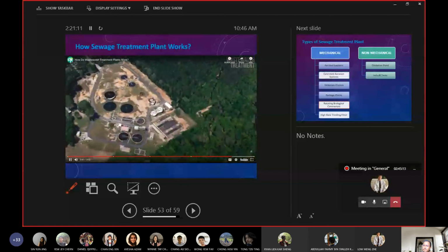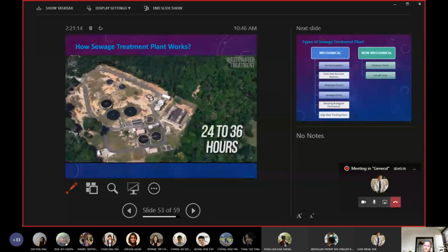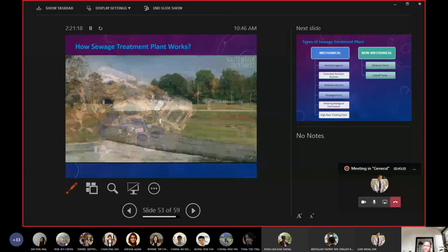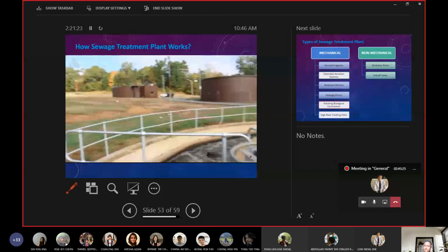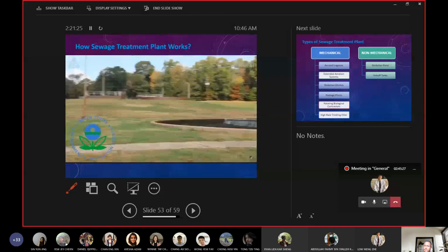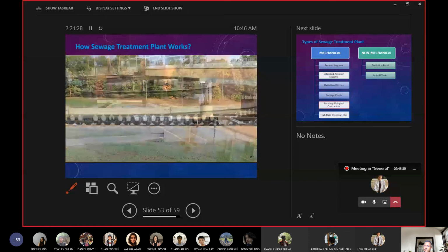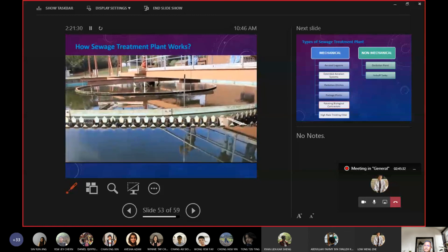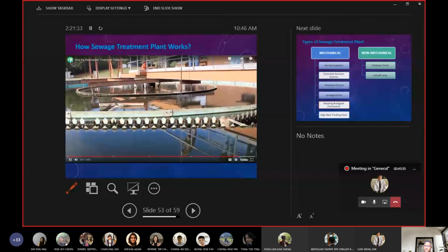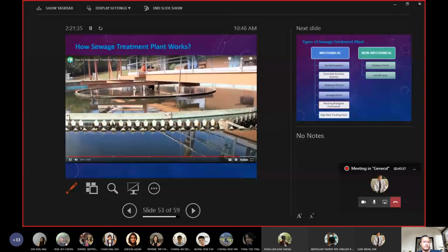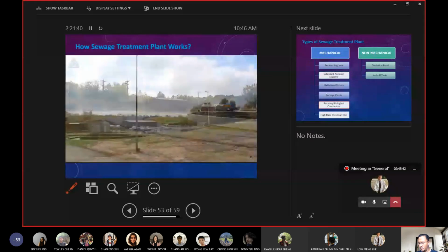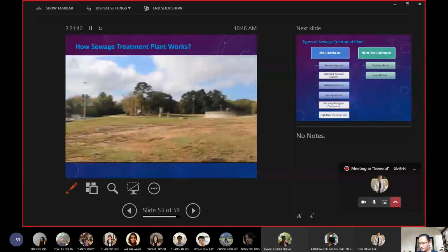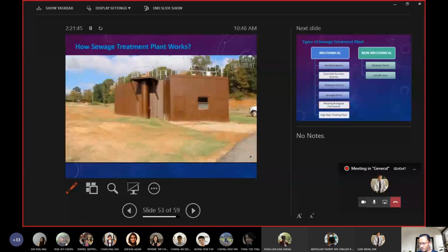The entire process of wastewater treatment takes on average 24 to 36 hours from when a drop of water enters to when it leaves. Each wastewater plant will receive a permit for flow rates, chemical levels, and effluent quality, among other things, from the EPA that outlines the necessary treatment for a plant. Wastewater plant operators will make adjustments to a plant's operation and constantly measure levels to ensure proper discharge and proper treatment. Without these operators and the dirty job that they do around the clock, our sewage would always stay sewage, and sanitation in modern cities would be much, much worse.